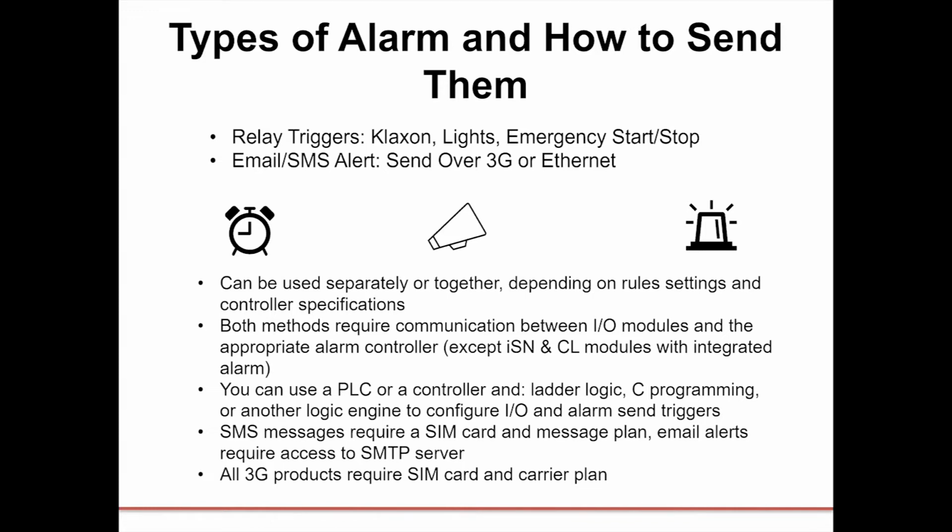It sounds just like your average home smoke detector, so some of those modules do have an integrated alarm. You can use a PLC or a controller or a PC, and ladder logic, C programming, or another logic engine to configure I/O and alarm send triggers. Any SMS messages are going to require a SIM card and a messaging plan, and email alerts will require access